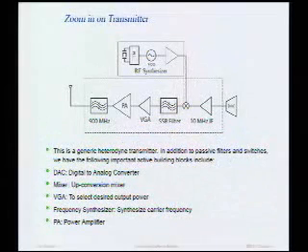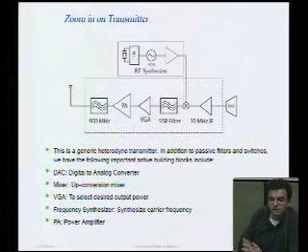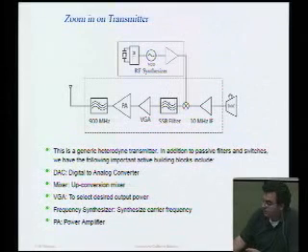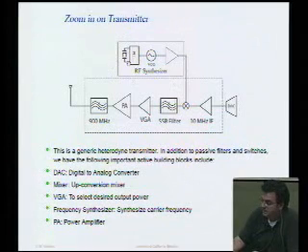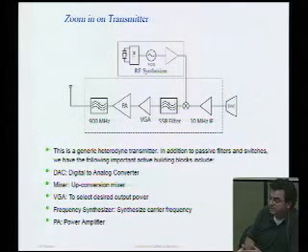Okay, a transmitter is a dual of a receiver, but it's very different. The kinds of constraints that you have when you build a transmitter are very different. In particular, a generic transmitter starts out with some digital bits, converts them into analog signals, and multiplies it by a local oscillator, which is generated by the synthesizer that we just discussed. There's that little crystal symbol that somebody brought up. This is our precise reference frequency. So now we've translated our, let's say, baseband signal, the bits, into a precise RF signal, very precise frequency.